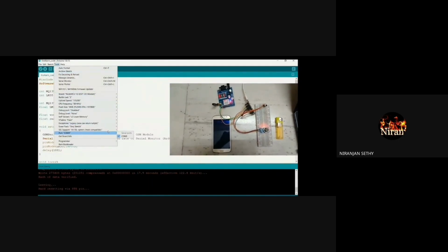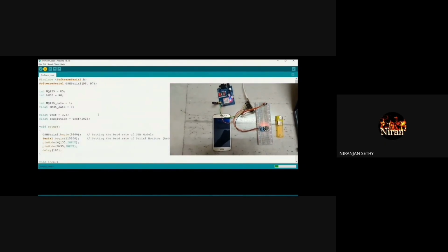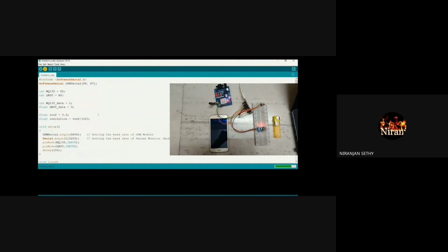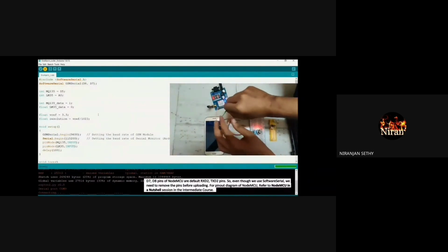Please validate that the appropriate boards and appropriate COM ports are selected. That's very important, as we say every time. Once it is all done, you can go for compilation. You can see that the compilation is successful and then uploading will happen. But it is not uploaded. Can you watch it? The upload is not complete. Why? There is a reason and we need to learn it. As we kept on telling you right in the beginning, and also in the previous set of courses, we are connecting the RX and TX of the GSM to Node MCU.